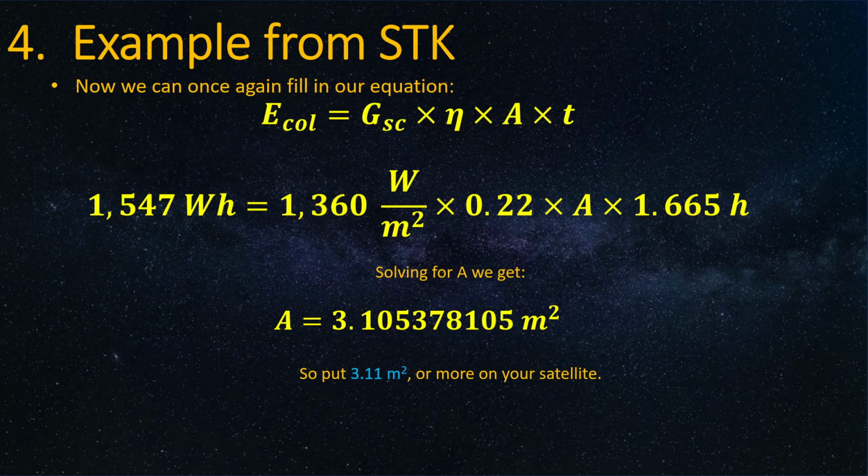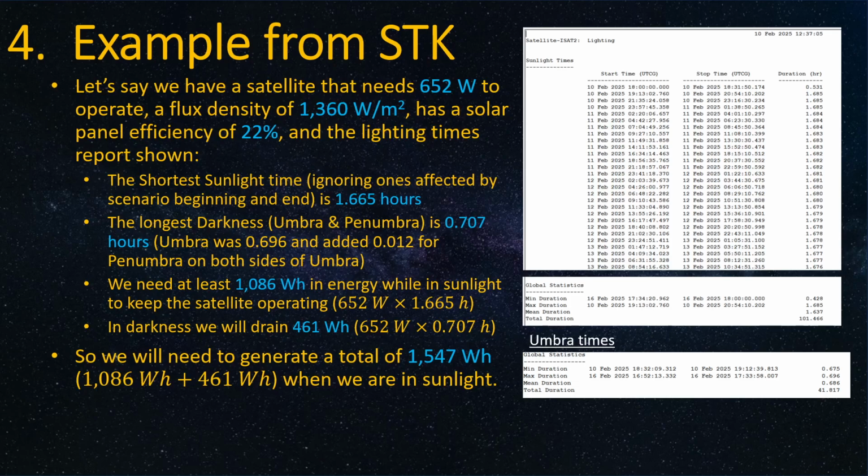The other nice thing about that is, if we know that we're going to need energy of, in darkness, say 461 watt-hours under our worst-case scenario, then when I look at the capacity of a battery, I know that as long as it holds at least 461 watt-hours, then we should be good with that battery. I don't necessarily need one that can hold 800 watt-hours.